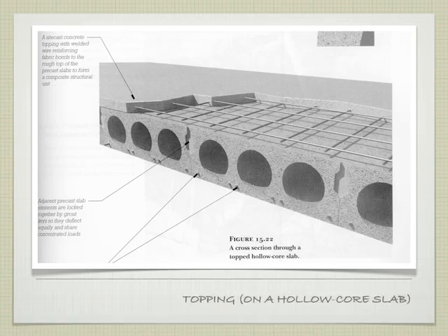Okay, so hollow core slab with a topping layer. Notice these are those cavities that I was talking about before. Those always exist to help tie the two slabs together. Sometimes they have the network of rebar that ties it together, depending on their scale. Sometimes it's just a keyway. And then we have the reinforcing running across the top, and then the 2 inches of topping layer on top of that.